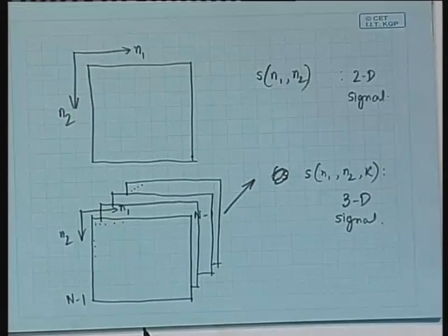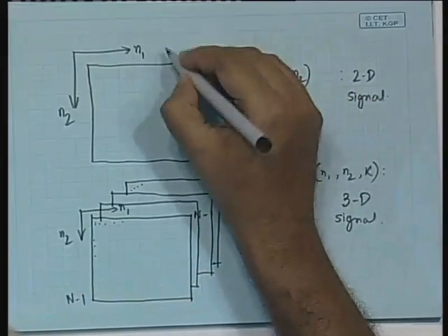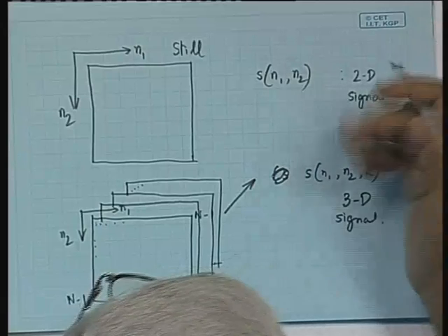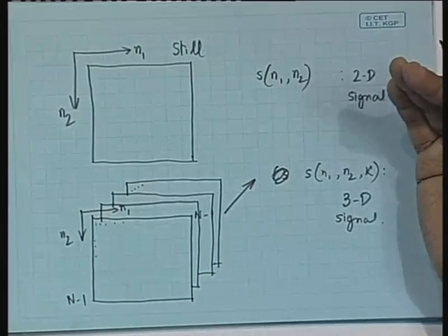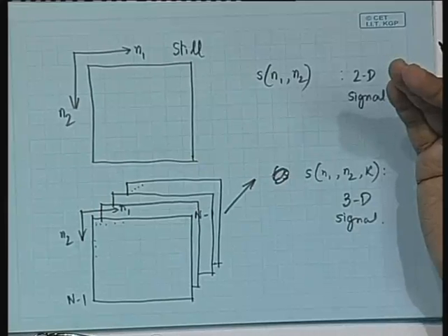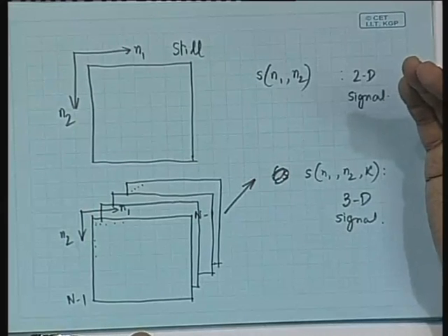But in this case, you take the image of a typical size. Let us take the size of an image to be 1024 by 1024, so 1K by 1K, which means there is 1 megapixel. If it is a still image, and we are having 24 bits per pixel, because for color images we have the R, G and B components, that means 24 megabits in one still image.